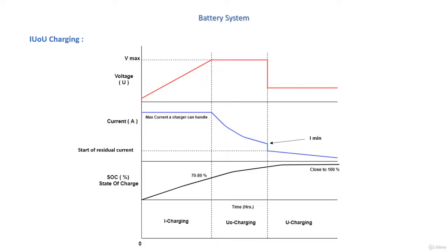So the charger supplies a very small value of current and decreases the applied voltage on the batteries to let them drop to a slightly lower voltage that is safe for weeks. The small value provided by the charger compensates the self-discharge of batteries. At this stage, the batteries will be kept near 100% of their capacity. Also, this stage helps the battery stay fully charged for weeks.